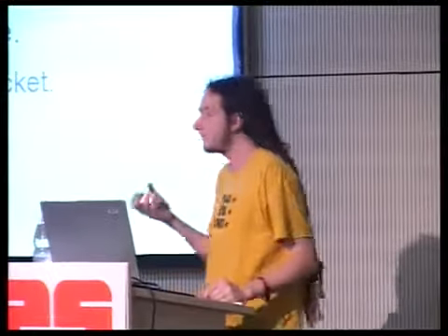So it checks it only at one moment in time, and it bases all of this timing on that single falling edge, which might not actually be a falling edge. If you make it already low and you guess at the moment at which it will start, then you can be sure not to knock its timing off. By speaking slowly, by sending your bytes slowly, you're able to send lots of bytes, have little error in interpretation, and at the same time not affect timing.